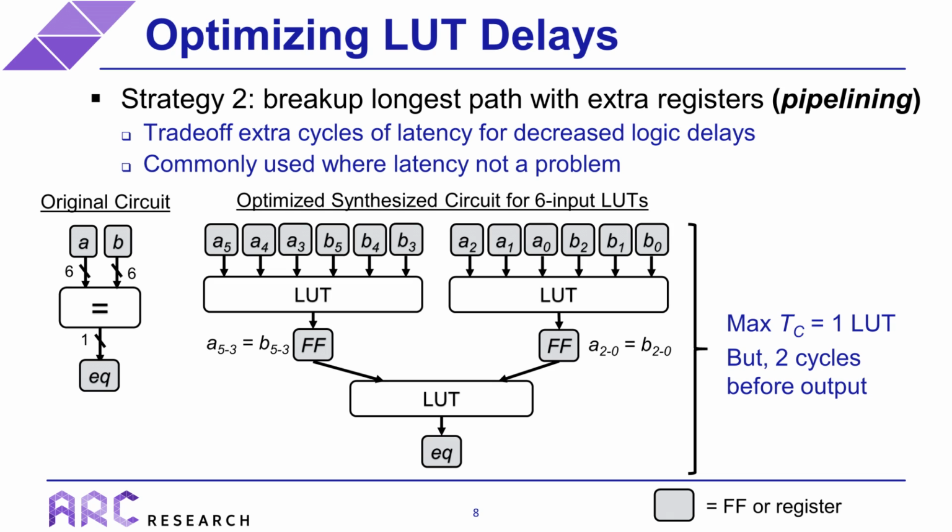of. So first of all, modifying latency by adding extra registers to a component can break the functionality of the rest of your circuit, which is why RTL synthesis tools can't do this for you automatically. So just be aware you might need to make modifications to the other parts of your circuit after pipelining one component, and those modifications could introduce new bottlenecks which require pipelining themselves.